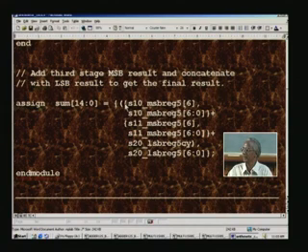These are the flower brackets used for concatenation, and once again concatenation here, and just to separate out, it is to sign extend here. So is the case with sign extension of this number. So the second stage MSB which are two in number, that is S10 and S11, are added here with sign extension, and to that we concatenate the LSB because we have added this earlier. So out comes the final sum here, 14 through 0.